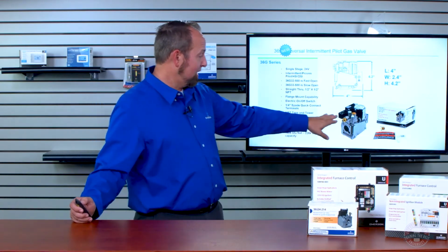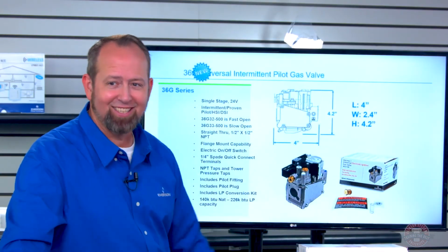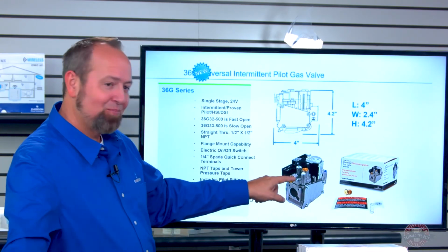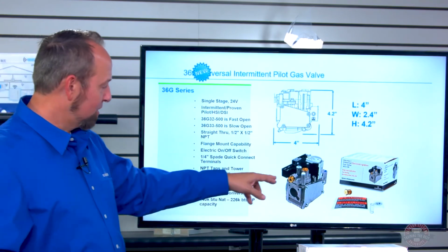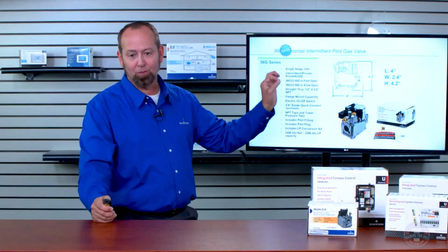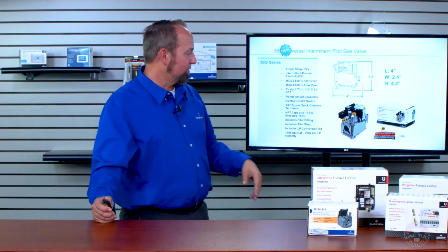Well, within the kit, and I'm sorry it's not shown here in the picture, I need to add that to my picture, is a plug that goes in that, so you don't push gas out the pilot tube. It's permanently plugged. It's not used. The same way with the top of the valve. You have the common, you have the main valve, and you have the pilot valve.